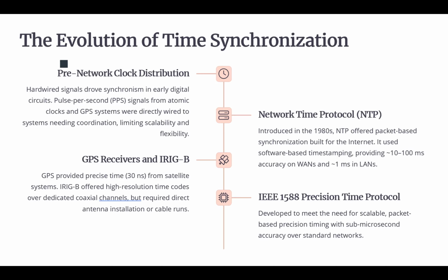To address those shortcomings, time synchronization evolved, and IEEE 1588 was introduced to define the Precision Time Protocol, PTP, so we could deliver very accurate time synchronization, down to a few nanoseconds.